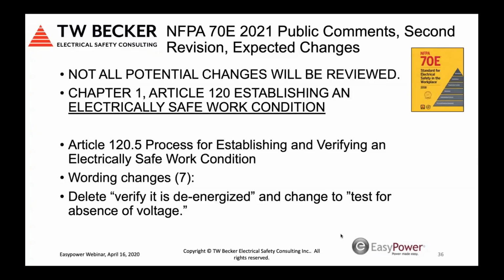Well, again, technical wording changes here. Testing for absence of voltage. That is the correct wording. We want to test for absence, right? So energized and de-energized, sure, but we want to eliminate the hazard, so we do that by ensuring we have absence of voltage.